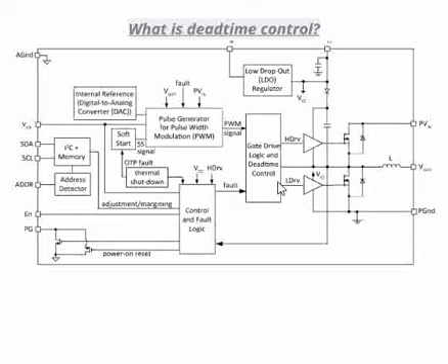So in switching regulators we use a PWM where the PWM switches these MOSFETs to have the required output on the V out pin. So what do we mean by switching? Switching means it's just turning on and off. Every one of us knows, right?